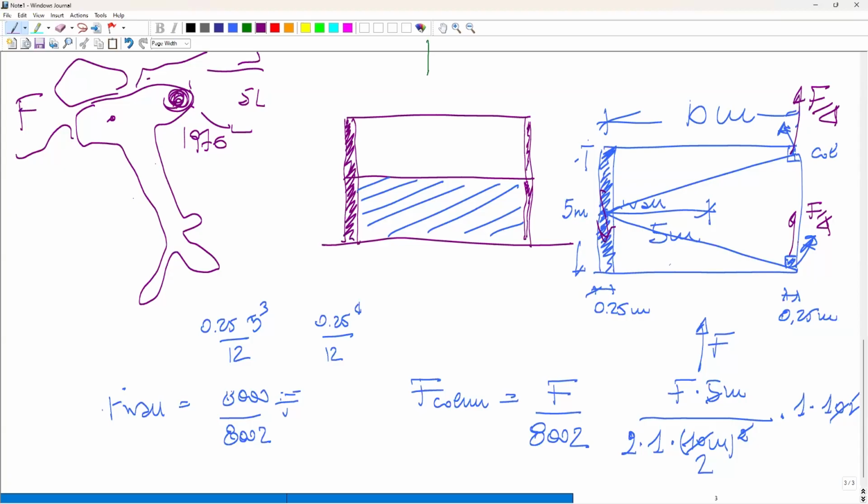Well, what did this result in? This resulted in a displacement demand that the column was not designed for. That column was designed just for vertical loads. But then you ask it also to undergo a shear force and a moment. And as we have said, in earthquakes it's not only a matter of resistance.